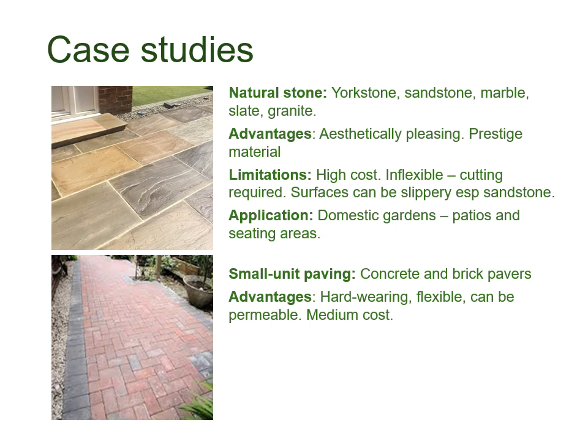Cost will largely depend on the use of the area and what needs to go underneath. So a block paved area for a vehicular access, or parking area where you're going to be parking a number of heavy vehicles, might need to have a concrete subbase.